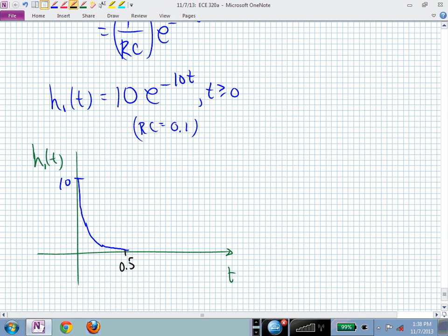So if I said our impulse response is 100 e to the minus 100t, that's even more like an impulse, and our output will look even more like our input. If I put in a square wave, the output's going to look more square. As I get more and more low-pass filter behavior, I'm going to round off those corners, aren't I? Remember our rounded tail from last time, and then we tailed off? That was because we maybe had low-pass filter behavior, or more low-pass than something like this.